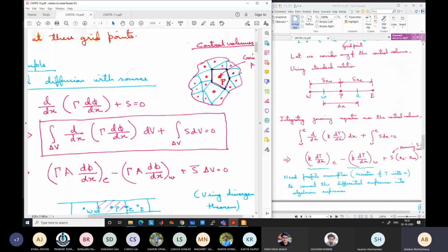Okay. So the discretized equation for this will have APTP is equal to A1 T1 plus A2 T2 plus A3 T3 plus A4 T4 plus A5 T5. Okay. All of them are unknown. So simultaneously we will have n number of equations and n number of unknowns, because we will develop equations for each grid point. So we'll have n equations, n unknowns, and we can solve it to find the temperature values, which we'll see later. Okay. So I have digressed. I was trying to show something here and I have forgotten what I was trying to show.